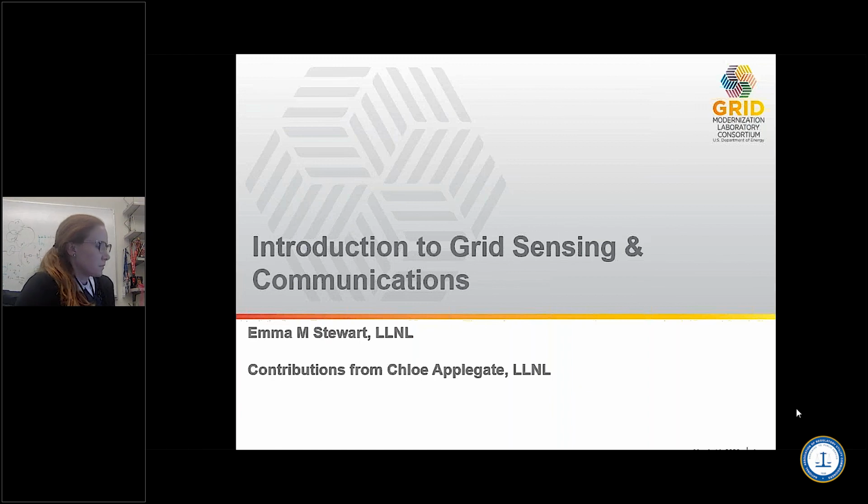Transformers can take surge loads that are higher than that, but the degradation in lifetime goes with a fourth power of overloading because of thermal effects. So while you can overload them, that will impact their life. So the idea is that you want to keep them below 100% at all times if possible. But this gets into a very complicated asset management discussion of, since these are so expensive, you don't want to load them at 25% because that's a stranded asset.